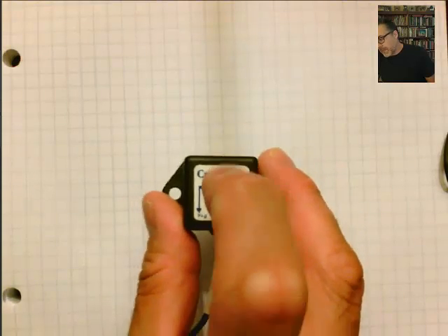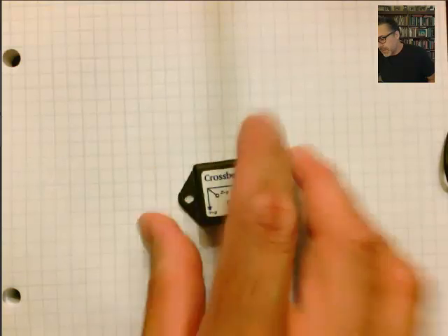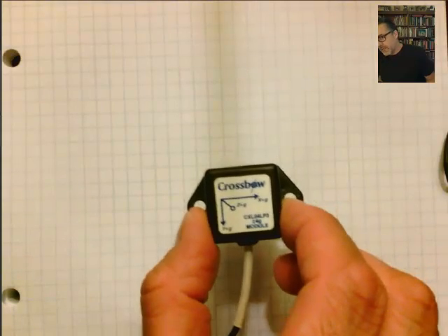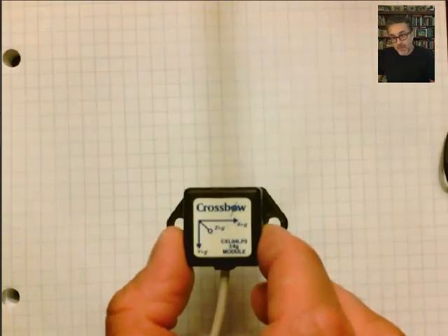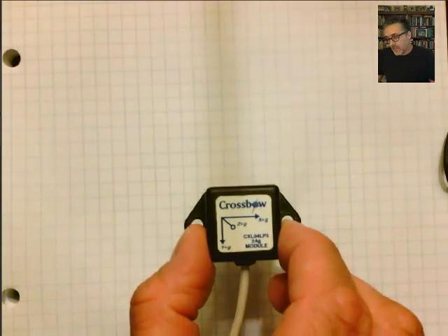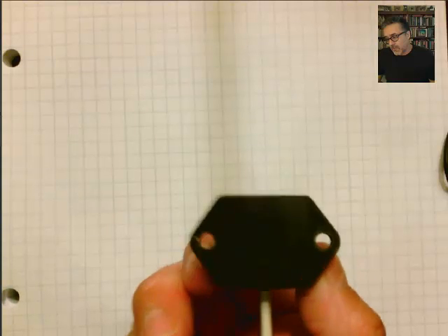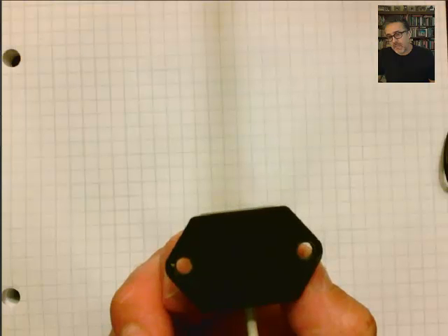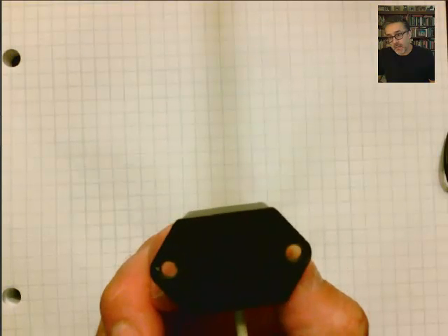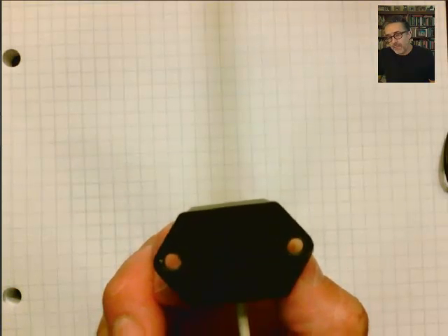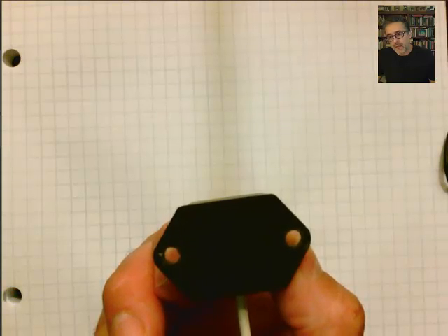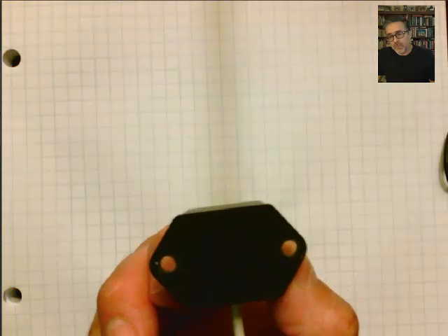If you're reading the z-axis, you take it from a positive 1G and convert that into a negative 1G. Think about that. You've changed it by how many G? By 2G, right? So the output voltage that you should see should change by the equivalent of a 2G excitation.